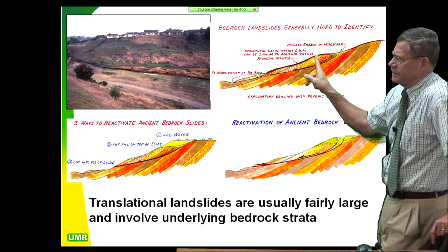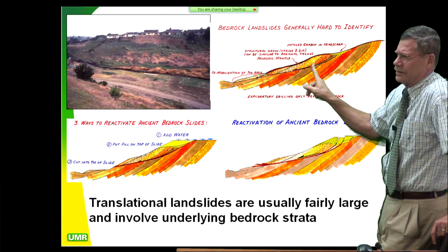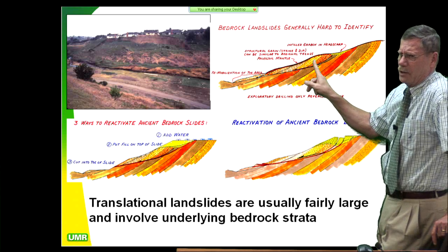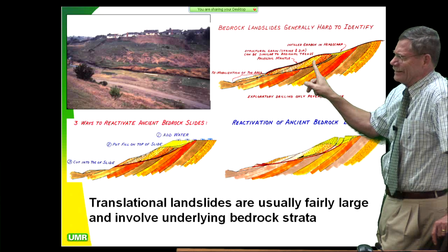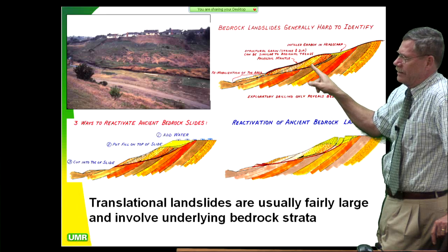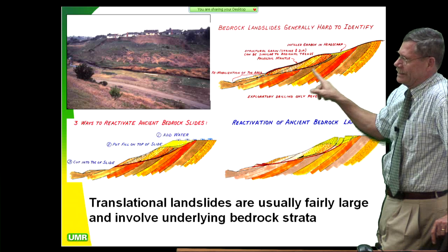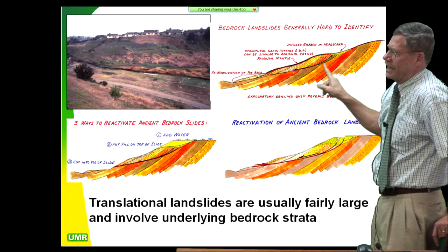If you go back and look at your data on it, there's a lot of little nuances to look for. One of the things here is very low relative density. 78 PCF is not the number you should have for a Miocene sedimentary rock. And that's what these things were. That's a low number for soil, uncompacted soil, in the 70s and 80s. And high water contents. The water content change between right here and right there was dramatic. It was 30 points. You went from a water content of about 37 down to a water content of about 12 right there. So you had a perched water system along that old ancient slide plane.